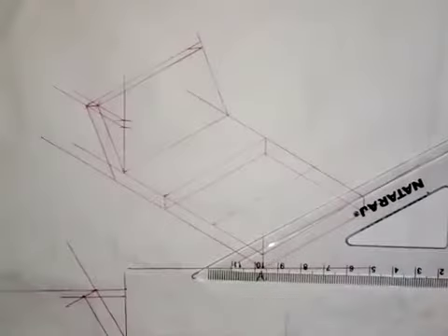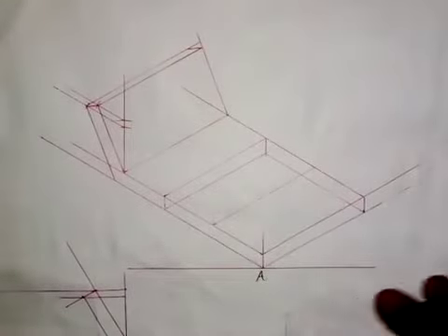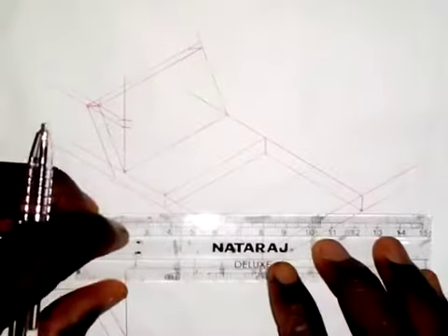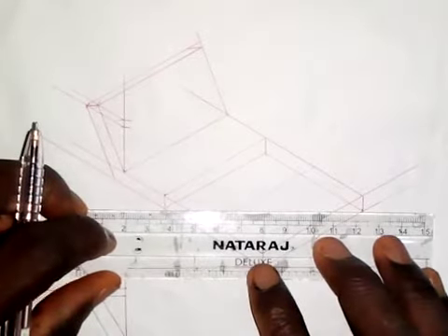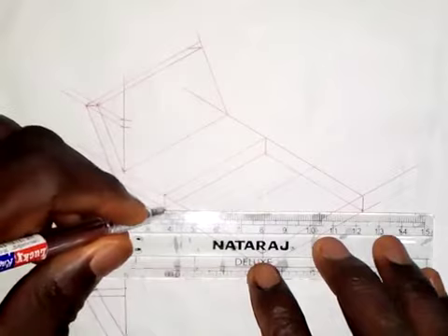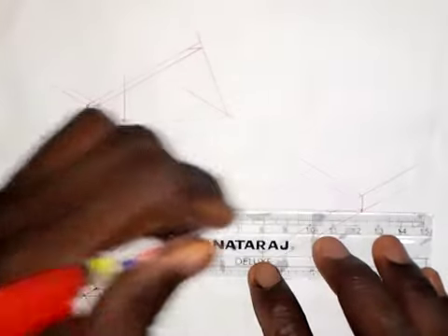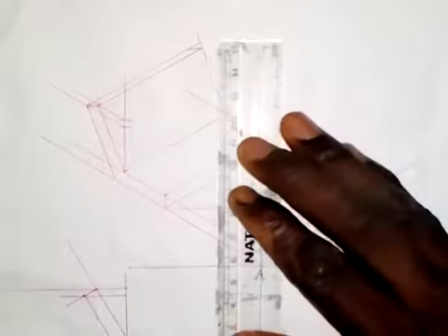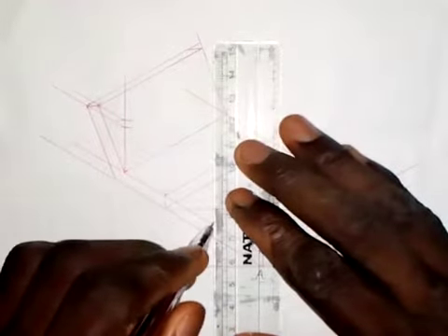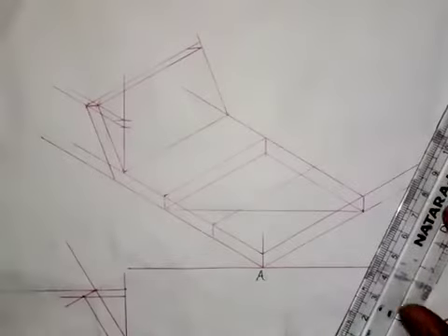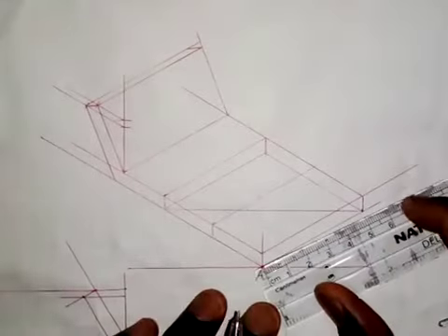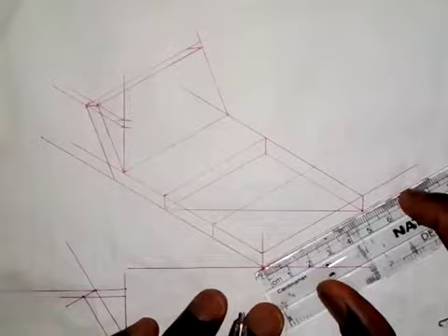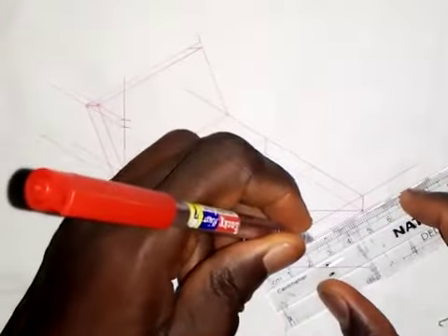Okay, now, having done that, the next thing I'm going to do is connect the longer diagonal. I'll connect them together. So I'm going to have many lines. Okay, so I'll connect that together. So I need to get this point here. So also I will divide this into 2 equal parts. That is 25. So this 25, I need to transfer to the other side.